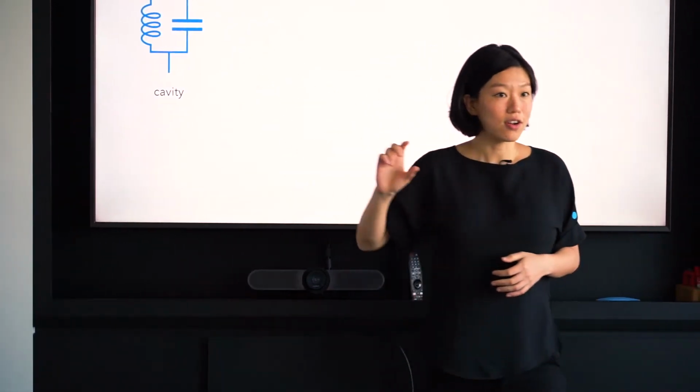Okay, so before we go into the details, I'll just do a quick 2-minute introduction of what circuits are, what superconducting circuits are. As I mentioned earlier, they are effectively just electrical circuits like capacitors and inductors put together in a way that allows them to show quantum behavior, right? One of the main ingredients is just a resonator or a cavity. It is really as simple as a capacitor and an inductor. We have different ways of physically realizing them, but conceptually they're very much like the standard electrical circuits.